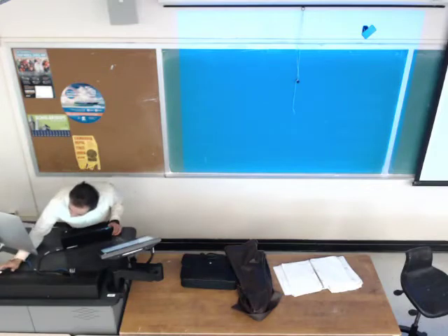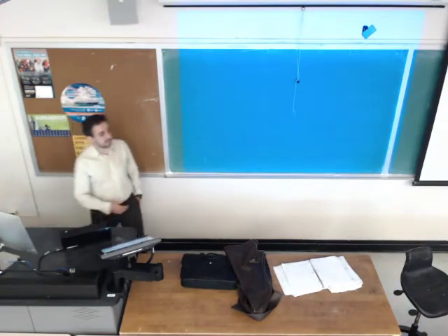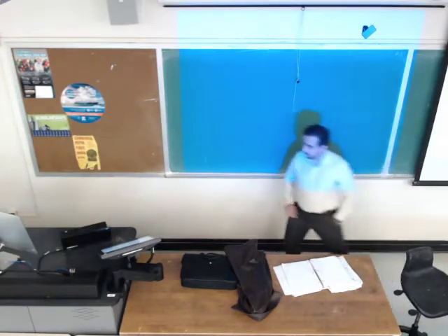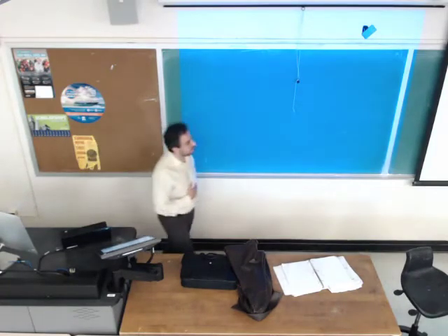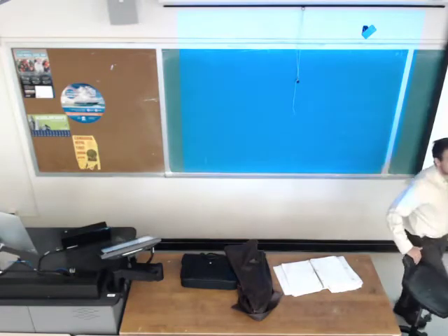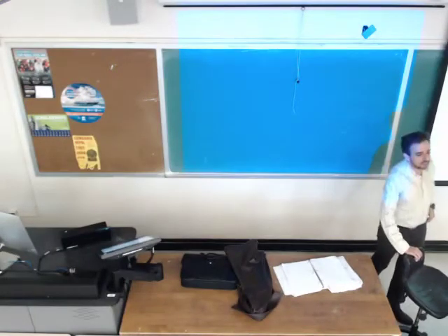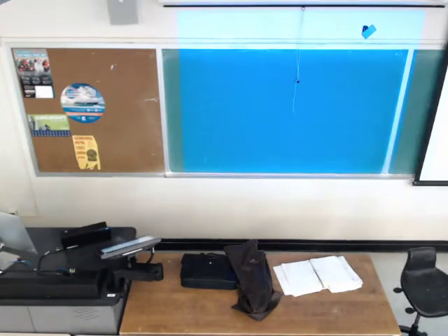So we are doing velocity analysis. We have started with an offset slider crank. We want to do velocity analysis for the offset slider crank. The first thing that we need to do, we should do the displacement or position analysis first to find the value for the unknowns, which are theta 3 and B or S in this mechanism.